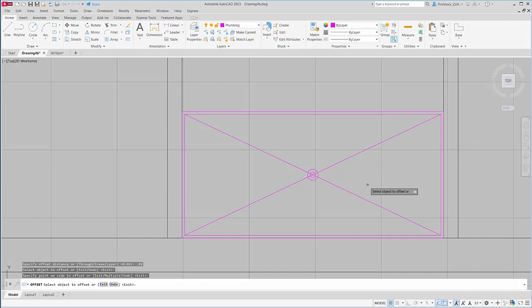Now I have a door in here as well. So we have a door enclosure, and it is 0.06 from the outer edge. So once again, I'm going to use existing lines, and then I can get rid of them. So 0.06. And this is where the door starts. And this is all based on manufacturer's requirements. And that door is 0.79 wide.